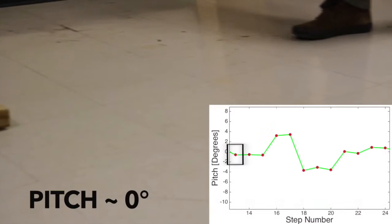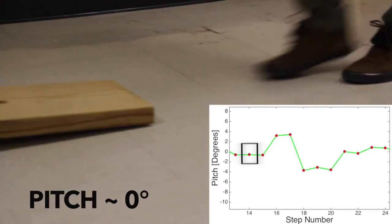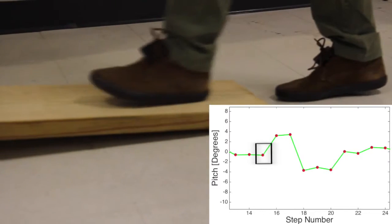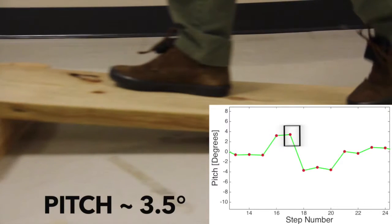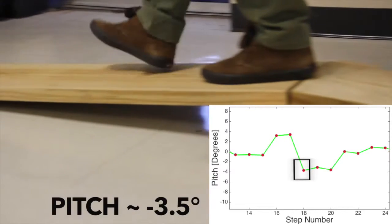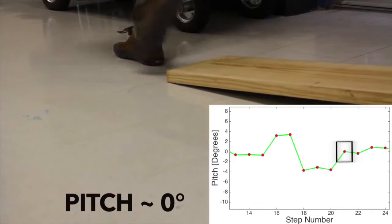Let's first consider ramp detection. When this person walks on a flat surface, the pitch readings measure an inclination of almost 0 degrees. As he walks up the incline, each step measures a positive inclination of the foot corresponding to the inclination of the ramp. Looking at the pattern in a window of past pitch readings, the algorithm determines that the pedestrian is walking on a ramp. As he walks down, the measured pitch reflects the slope and gets back to 0 on flat ground.